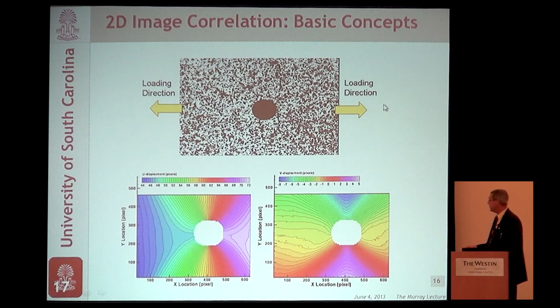Here's a simple example. In this case, we see this all the time. We have a plate with a hole. In this case, it's a rubber plate to give a lot of deformation. And you can see the fidelity of the deformations that you can measure. This is the horizontal displacement from low on this side to high on this. And this is the transverse displacement with the contraction inward here and the contraction inward here shown up clearly visible in the measurements. The noise here is quite small. And as a result, the method works really well.